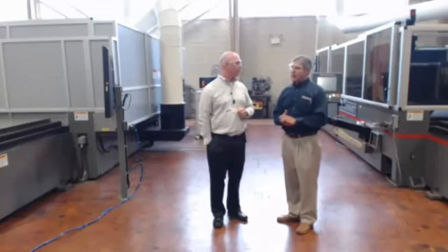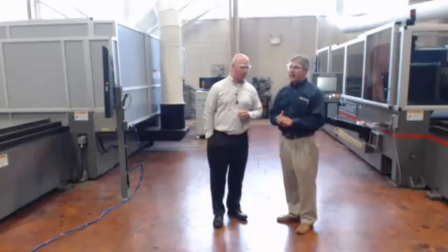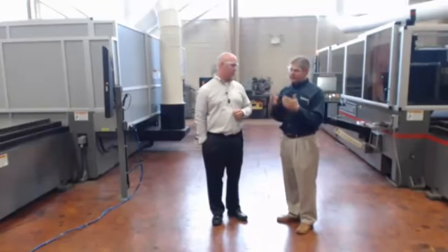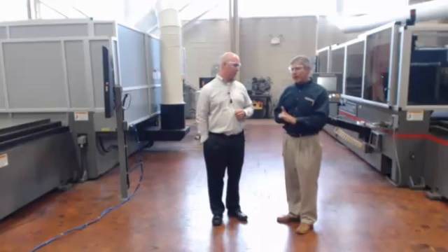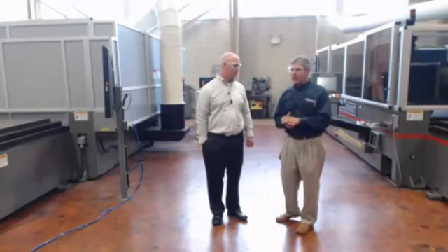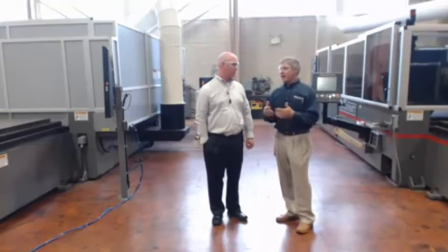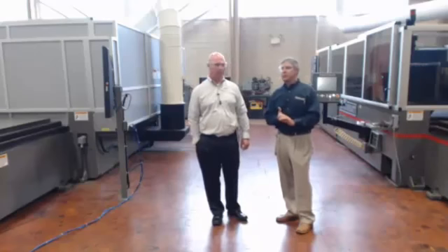Right, and on these thinner parts that you saw cut here, there is a dramatic difference in the feed rate. The standard feed rate on this fiber machine for 20 gauge was, I believe Drew said, 2,000 and some change, and it's probably 4 or 5 times less than that on the CO2. So with the faster fiber machine, taking the extra time to cut the Slug Destruct is not as detrimental to overall productivity as it would be on a CO2.